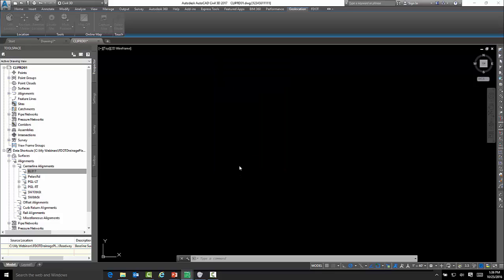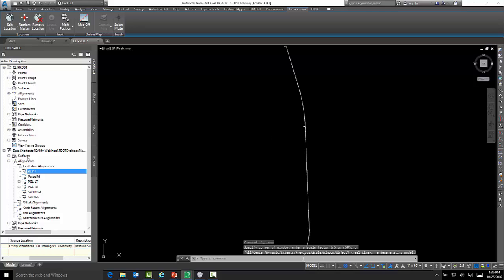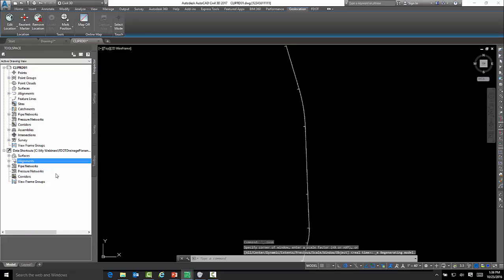And click OK. Once you click OK, double click on the wheel of your mouse to perform a zoom extents if you don't see anything in your drawing.